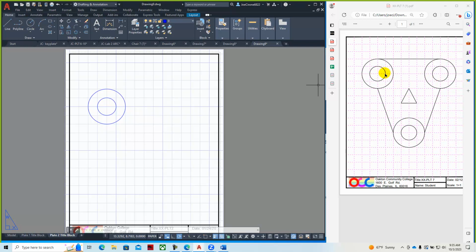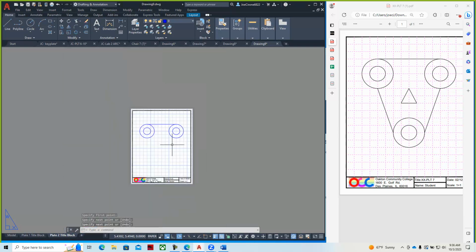And if you count each square as a half an inch, you could just count 1 inch, 2 inch, 3 inches, 4 inches over. Sometimes I'll make a construction line like that, 4 inches, and then I'll erase it afterwards to keep my measurements accurate. But there are videos on how to create this. Notice that it works well because OSNAP is not on. So when OSNAP is on, it will give you some problems sometimes. So be careful and make the drawing without the OSNAP command.